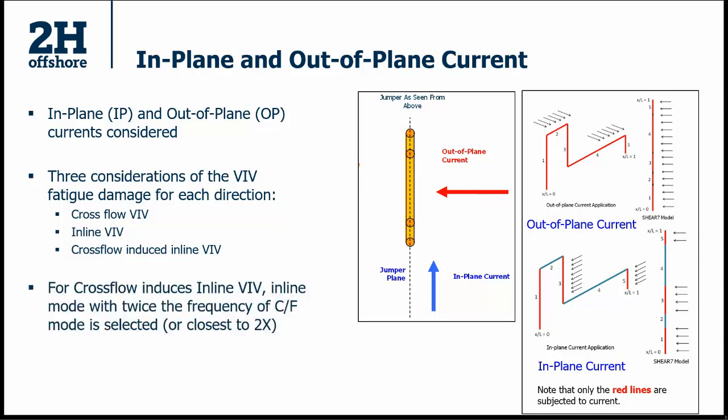Another thing to note is that when you get cross-flow induced inline VIV, that vibration occurs at twice the frequency of the cross-flow mode. So in doing this analysis, you tend to choose a mode of vibration which is close to 2 times the frequency of your cross-flow mode.